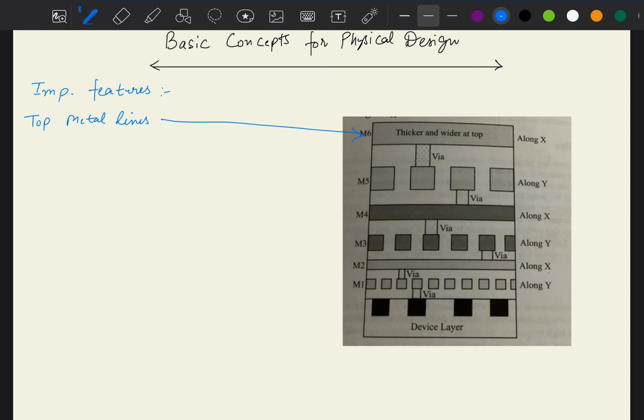So now coming to the resistance part, what we have to take into account when considering the resistance. At high frequency, current tends to flow on the conductor surface and the core of the conductor remains effectively unused. As a result, at high frequency, the resistance of an interconnect tends to increase.